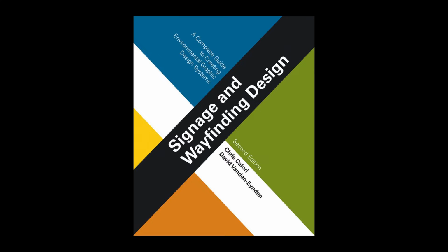Architectural and site factors affecting mounting. As clearly stated throughout this book, signage programs exist within an environmental context, be it interior, exterior, or both, and the EG designer needs to consider the physical characteristics of the environment within which the signs are to be mounted. Ceiling clearances, wall and corridor widths, obstructions such as columns or trees, and other elements will affect sign mounting decisions.